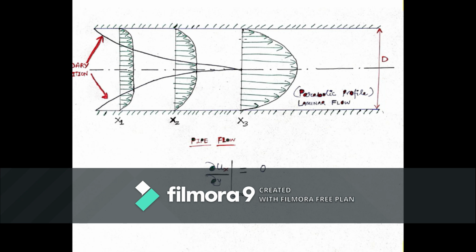After the entrance length, you have a fully developed flow where you have a parabolic profile for the laminar case, and here the gradient becomes 0 at y is equal to 0, which is the center line of this pipe. So at y is equal to 0, the x component of velocity is constant and the gradient is 0. This is a natural boundary condition which is known as Neumann boundary condition.